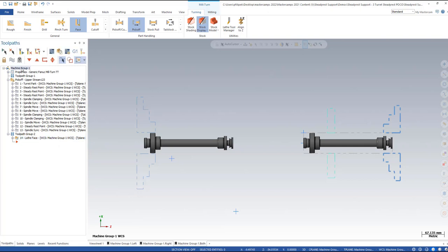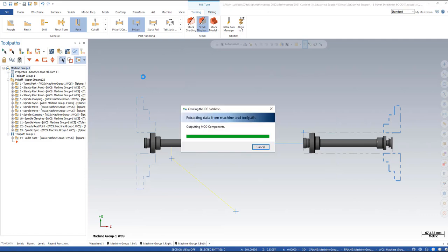Now let's go ahead and select all of our ops here. And as you can see, my pick-off routine, like always, kicked out a whole bunch of operations as far as spindle syncing, clamping. But you're also going to see in here there's a steady rest point, steady rest point, steady rest point, steady rest point. And that's going to position, clamp it, move it with the transfer. So once I come into the G1 button here and launch this out, we're going to have to do a little bit of work in the sync manager.